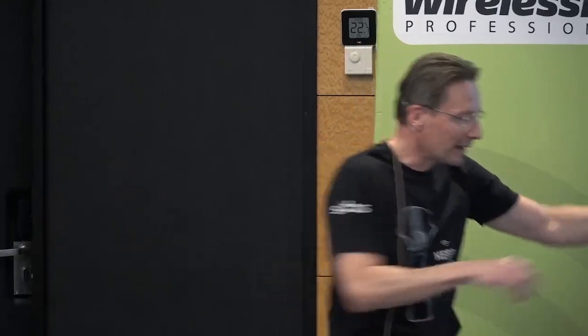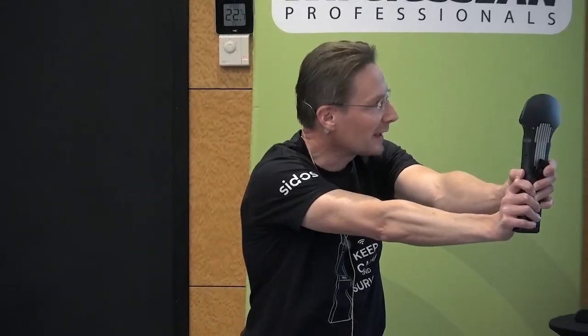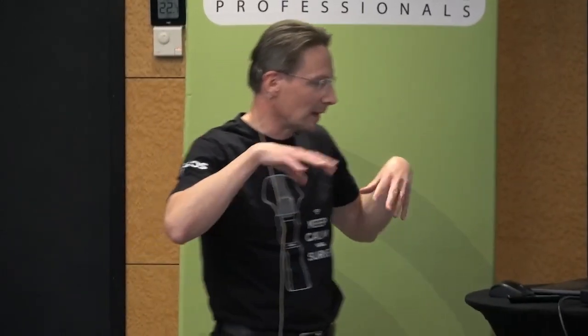Unless the building changes, which it doesn't, I can stop and measure an average for a long time and get -48. Then I give this to Keith, and he stands in the same spot, except 2 inches or 6 centimeters this way, and he measures and gets -40. Then we argue for an hour which one of us doesn't know how to measure, and I'm not presenting here next year. But we are both wrong and we are both right. It's these tiny ripples in this field that we see here, okay? So the myth that signal strength changes smoothly, and therefore you can define it accurately, is not true.